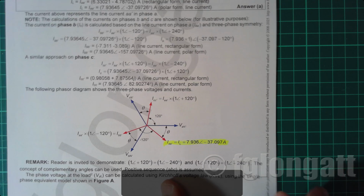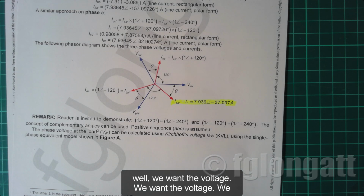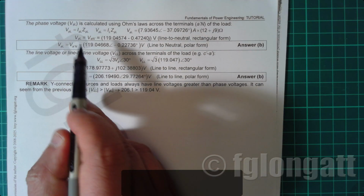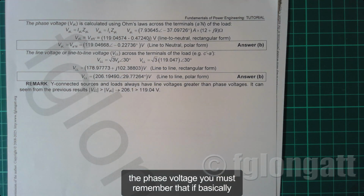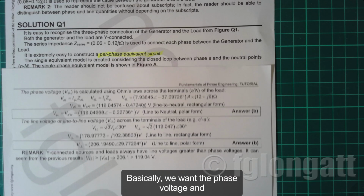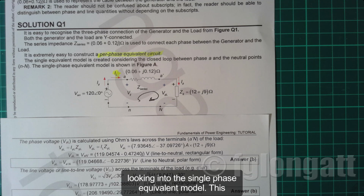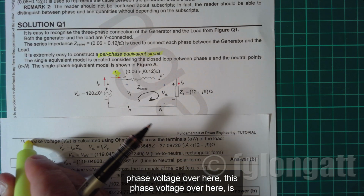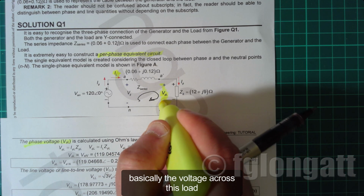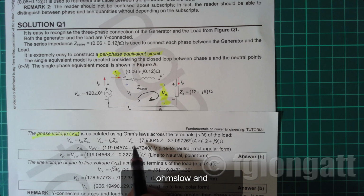So next step, continuing with the solution, we want the voltages. We want the phase voltage, and the phase voltage, you must remember, is basically the voltage drop. Let me go to the equivalent circuit here. Basically, we want the phase voltage, and looking into the single phase equivalent model, this phase voltage over here is basically the voltage across this load,